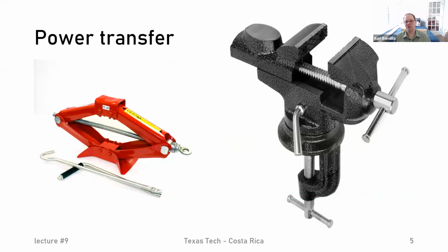When we change a tire, we usually have this little tool, something that looks similar to this, might have a different shape, but this is to lift the car up so you can take the tire off the car. Call it a car jack. The way that it works is we're using one of these rods here to connect here to turn, and it's turning that turning motion into a lifting motion. It does that by this thread right here.